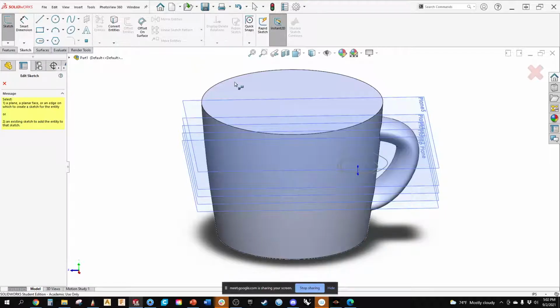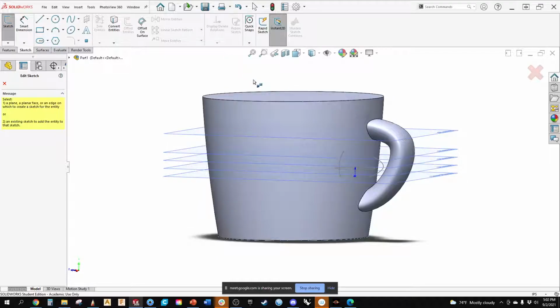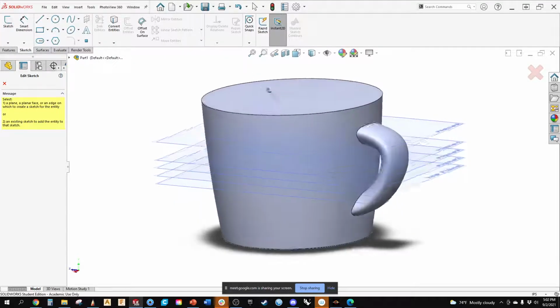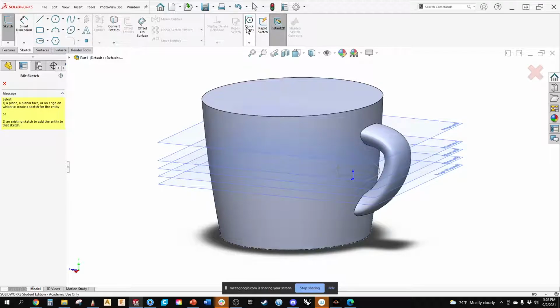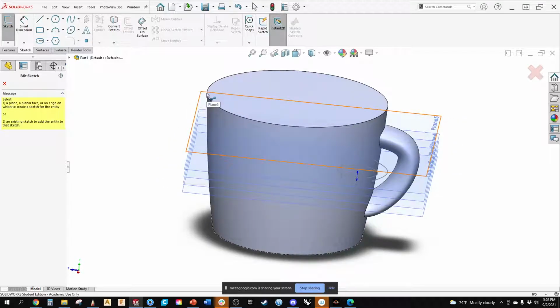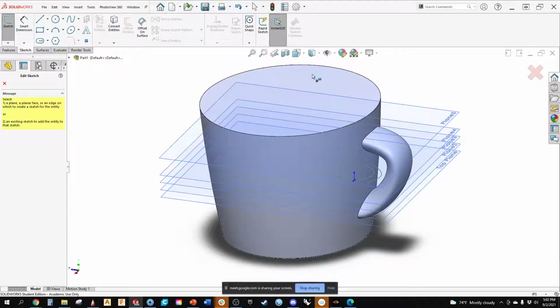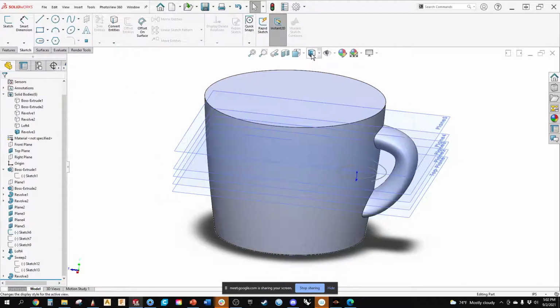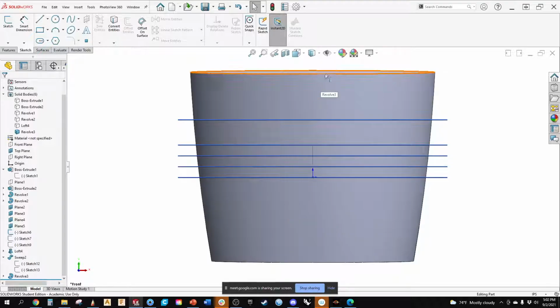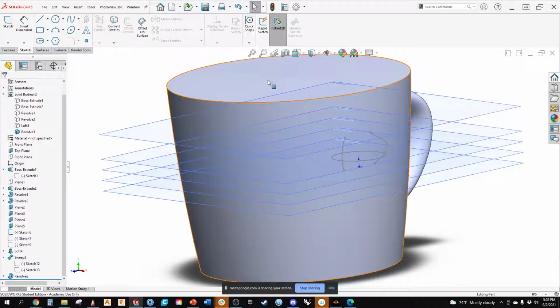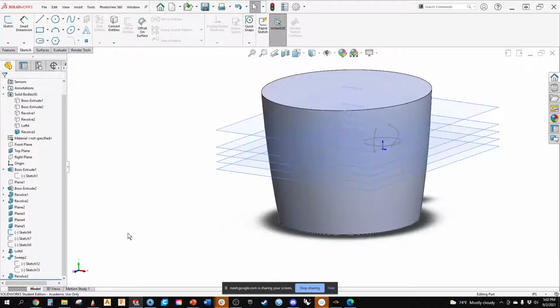So we can come here. Oh. So here's a fun thing. I can create a sketch on a planar surface, but it's not letting me do that on here. The moment I can't do something like that, well, why is it not letting me select this face? To me, that's always a, hey, there's a problem here. What that probably means is, for some reason, that's not a planar face. So you can kind of see that it's curved. If that's supposed to be completely flat,